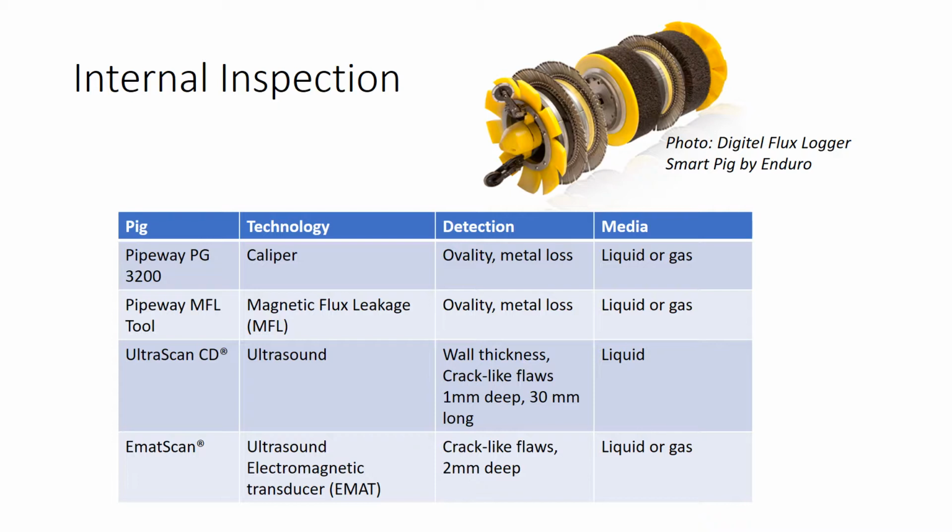Pigging has its challenges and is not always economically viable. Pigs can get stuck in tight bends or if a pipe wasn't properly cleaned. They also require pig entry and exit stations. Not all pipelines, particularly older ones, are piggable. A friend of mine who is a chemical engineer, who has been disgusted with the troubleshooting associated with smart pigs, once told me, "No pig, no problem."